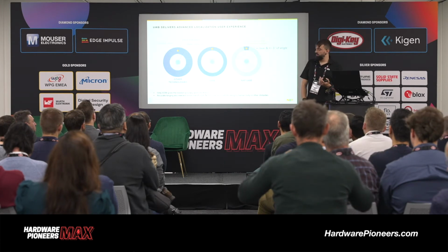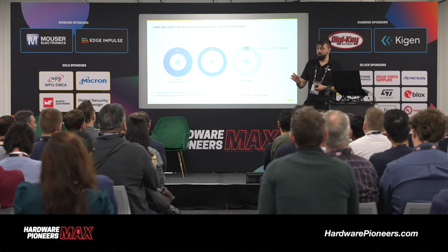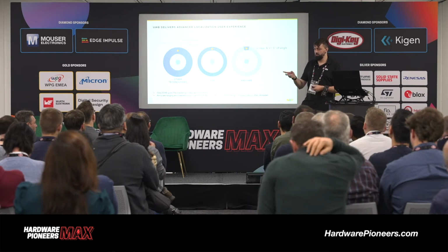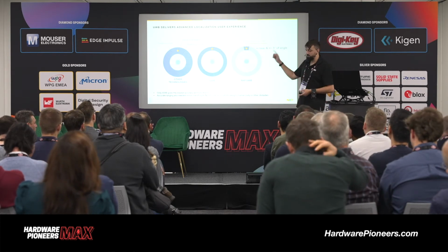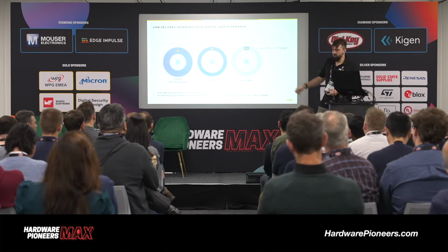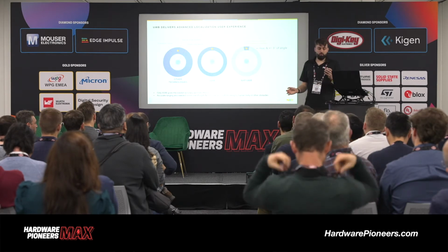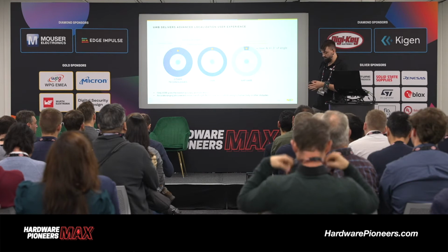But if we include also the angle of arrival, we can have a very narrow position determination between only two devices. We can have plus minus 10 centimeters and plus minus 3 degrees of angle, which is an awesome improvement over existing ranging techniques.